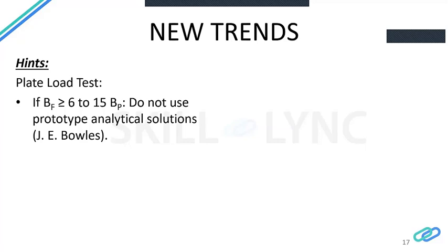For example, the analytical solutions or equations you are using are limited to what we call the half-space elastic solution, meaning the soil is homogeneous and infinitely extends to a large depth. But usually this is not the case, and you have certain limitations in layered soil. If you have a layered soil, then the use of this plate load test in the design is not as straightforward.